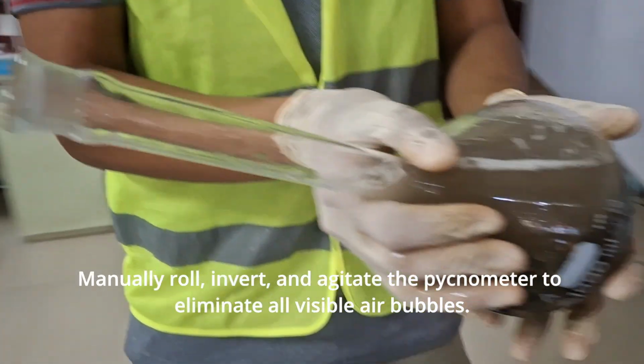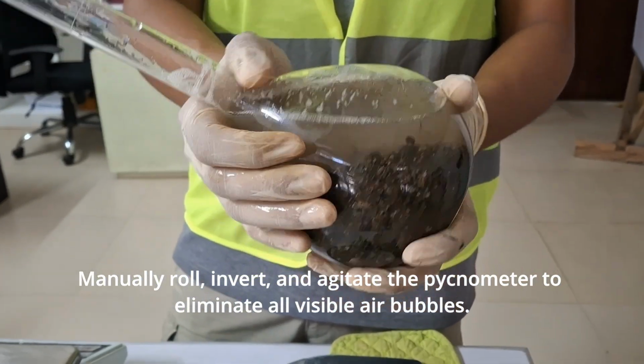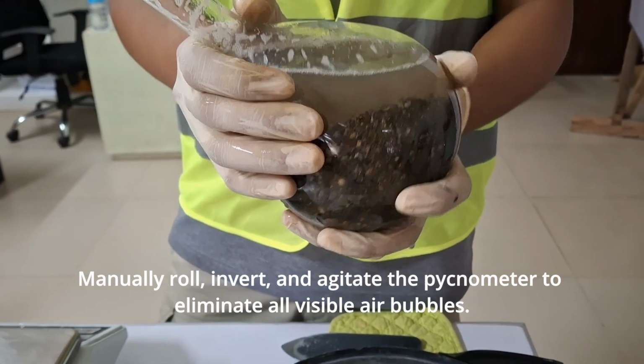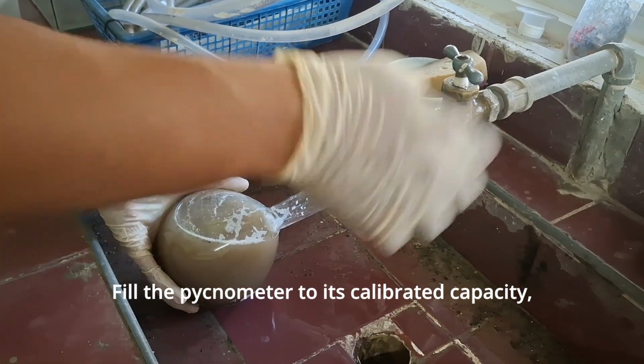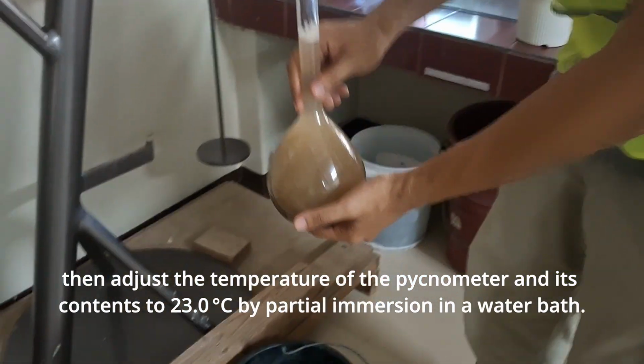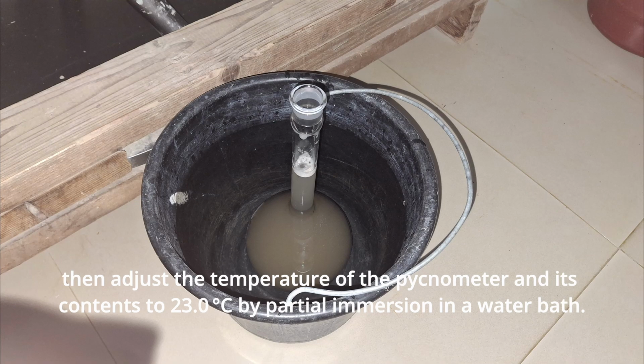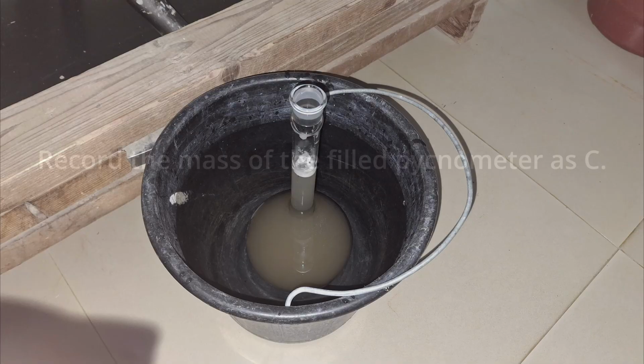Manually roll, invert, and agitate the pycnometer to eliminate all visible air bubbles. Fill the pycnometer to its calibrated capacity, then adjust the temperature of the pycnometer and its contents to 23 degrees Celsius by partial immersion in a water bath.